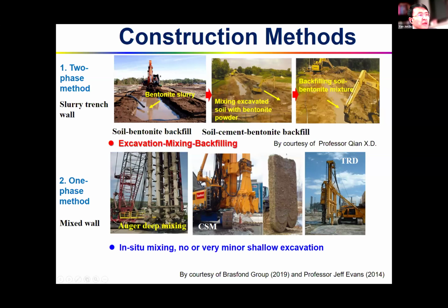It's a mixed wall conducted with auger deep mixing, CSM or TRD, where CSM and TRD are very advanced construction equipment. In this method, there is mixing with no or very minor shallow excavation. All those photos are from Professor Jeff Evans, who was working in Bucknell University and is my good friend.